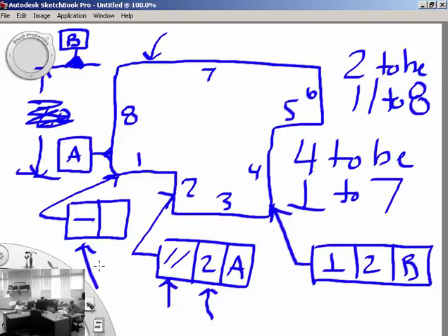Okay. Now, what goes in the box after it? 2, your size. Now, we don't really have to have a datum associated with this particular choice. It's just straight, okay? So they can sometimes be given a datum, but not always. So you may see it either way. They may relate to a dimension or something of that nature, but for the most part, we could get by with just understanding this thing needs to be straight.